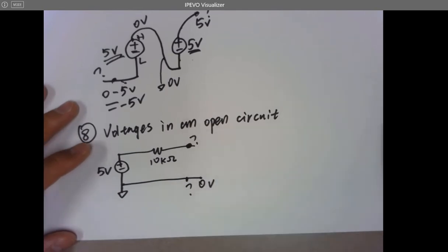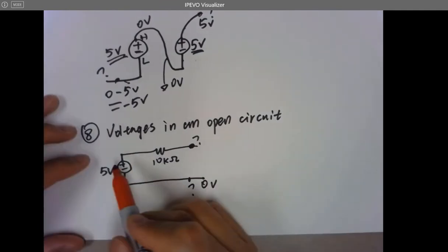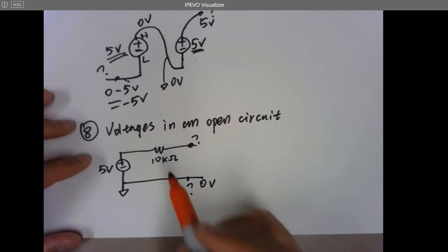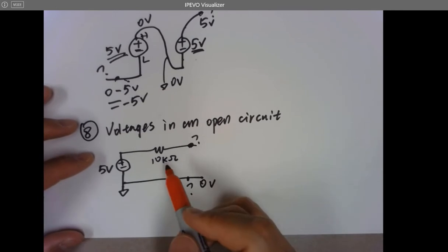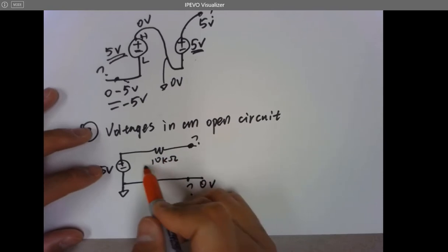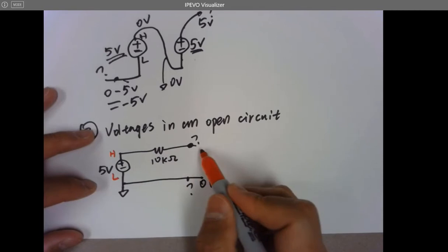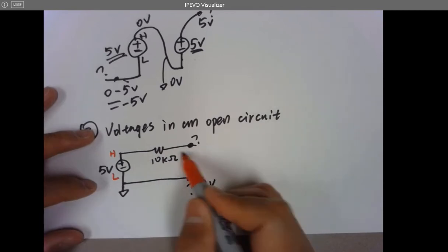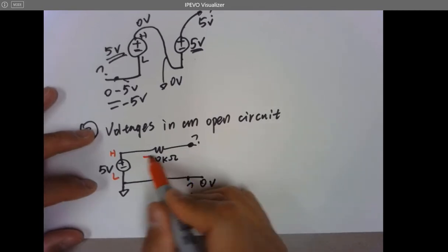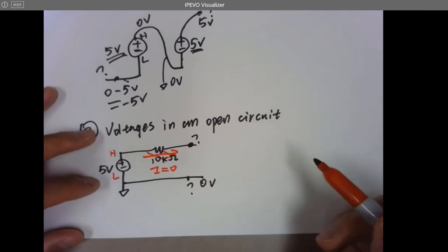However, it's wrong because keep in mind, in Ohm's law, if there's no current flow, there won't be any voltage drop. Okay, so which means there's no current, right? So you're thinking this is a higher voltage, lower voltage, so it's going to pump the current. Wait, there's nowhere to allow the current to flow. So there's nothing. Or we can say the current is 0, right?